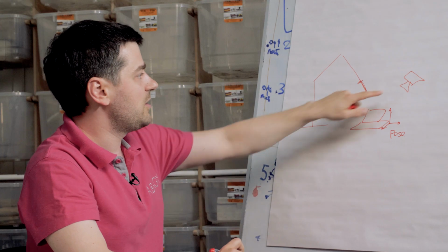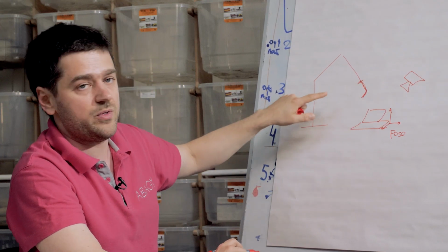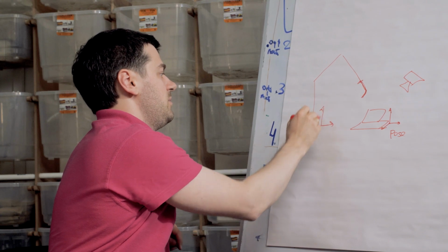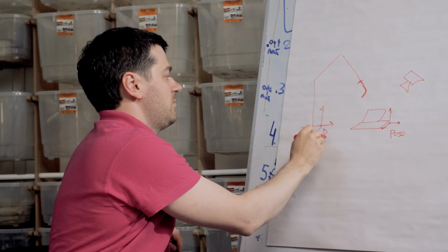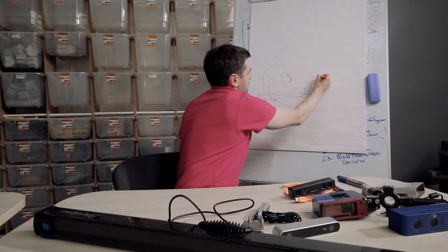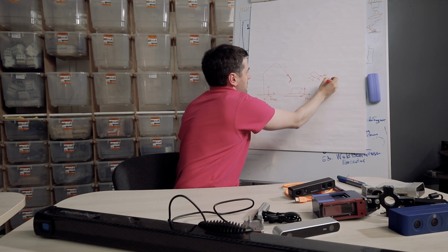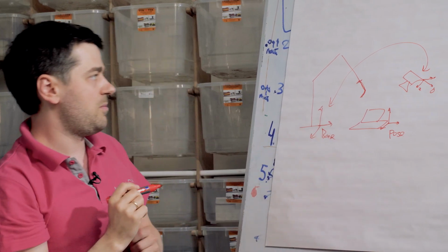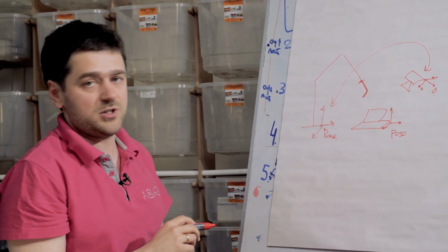And we need to calibrate the camera along with our robot. Usually it's some robotic base, for example, this coordinate system. So knowing the position, the coordinate system of this camera with respect to the base of the robot is called extrinsic calibration.